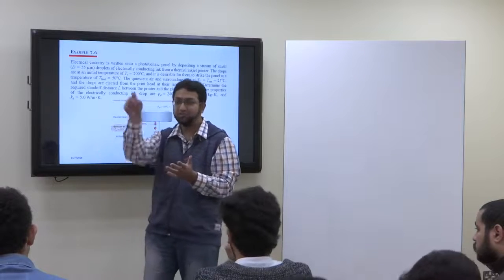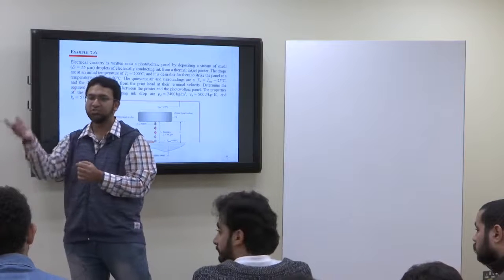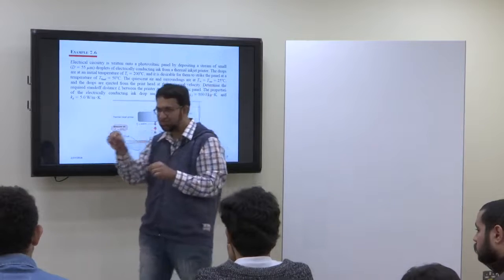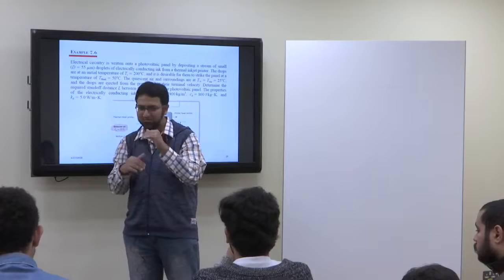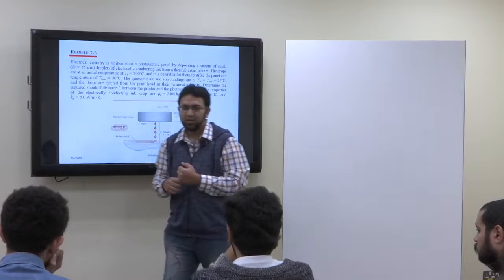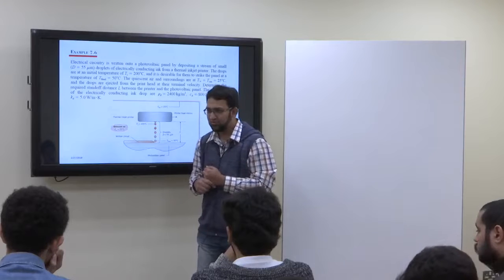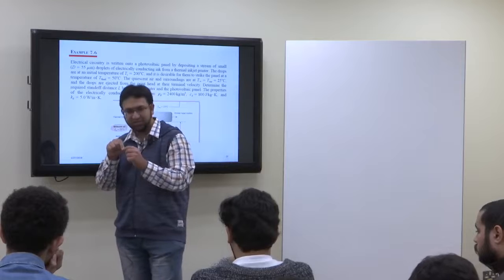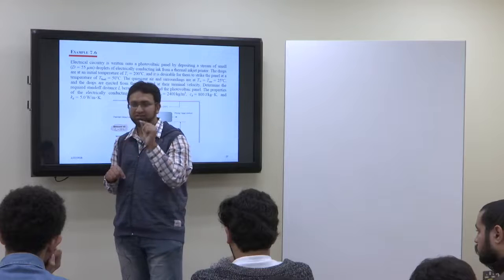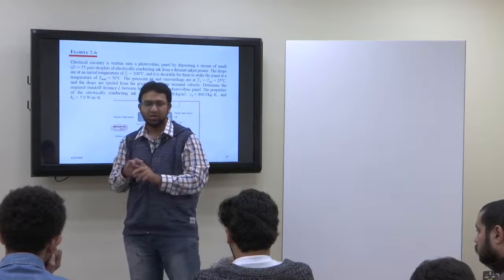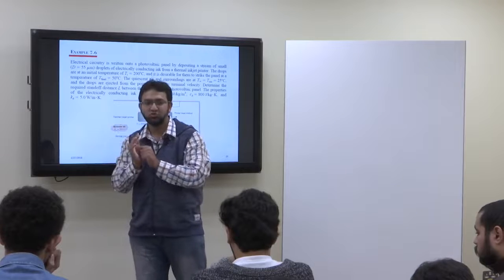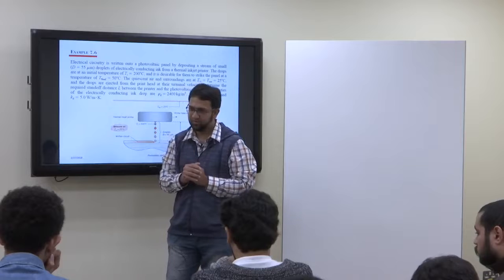So the effect of gravity is not acting when the body is moving at the terminal velocity. Effect of gravity is the acceleration. If there is acceleration, then velocity should increase, but the velocity is not increasing. That means the acceleration g is there, but it is cancelled by the other forces, buoyancy force and the drag force. So the velocity is constant. Now when the droplet leaves the inkjet, it is at around 200 degrees centigrade. The better thing is that when it falls on the photovoltaic panel, its temperature should be around 50 degrees centigrade.